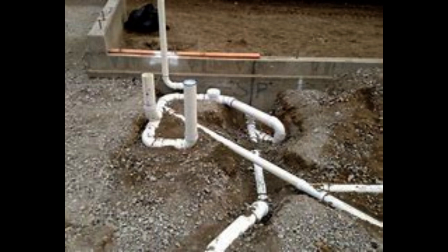C. Hydromassage therapy equipment. 1. The inspector shall report as deficient: A. Inoperative units. B. The presence of active leaks. C. Deficiencies in components and performance. D. Missing and damaged components. E. The absence of an opening that would allow access to equipment for inspection, service, repair, or replacement without removing permanent construction or building finish. And F. The absence or failure of operation of ground fault circuit interrupter protection devices. 2. The inspector is not required to determine the adequacy of self-draining features of circulation systems.